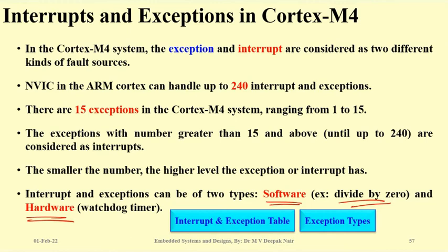So what will happen? It can generate an interrupt or an exception by the microcontroller itself. Maybe you have not written a separate interrupt service routine, but because this type of condition has to be handled, exceptions are defined in the microcontroller.